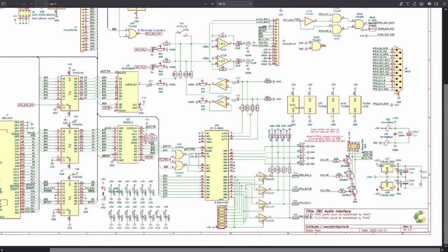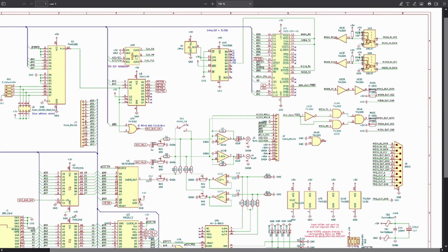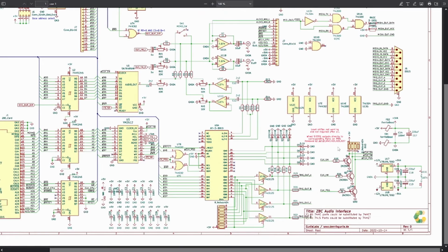Right down here, since those are 3.3 volt signals and not 5 volt signals, I thought it would be a smart idea to add those level shifters. Unfortunately, as it will turn out in this video, those won't work at the desired frequencies, will cause a lot of pain, and I'll end up, spoiler alert, leaving them out. But you can still watch me trying to troubleshoot the circuit and trying to come to a conclusion.